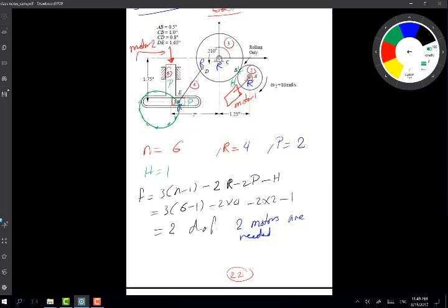You can fix link number 6 at different positions, ground it at different positions, and every time you get a different linear motion for link E, which is a slider. It will slide left and right, yes, but will have different particulars, if you like, depending on how high or how low you decide to fix link number 6.